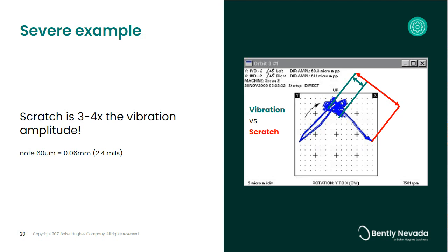So that's significant. If somebody saw that, this is getting close to an alarm level, but the actual vibration itself isn't that bad. The machine is operating quite well, but the total indicated vibration, the combination of the actual vibration plus the noise, plus the runout, is quite severe. So it can lead to inappropriate or inaccurate machine health decisions and machine maintenance decisions.